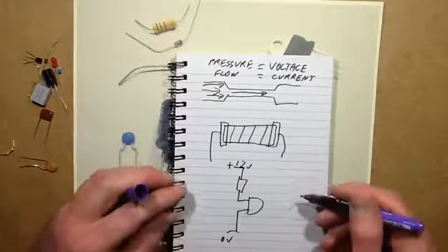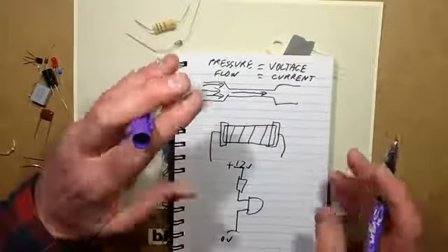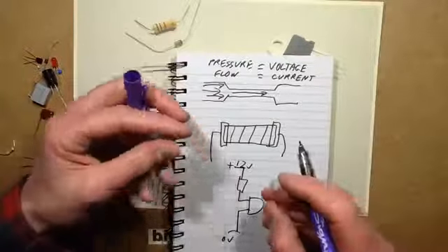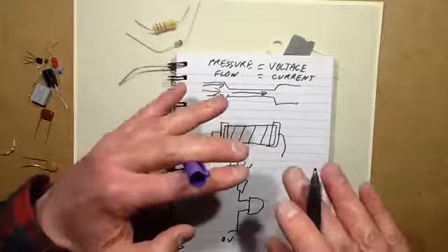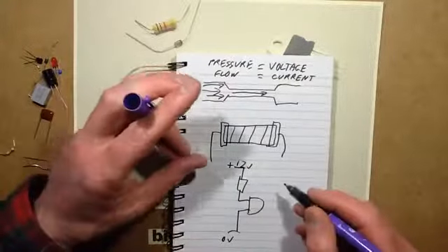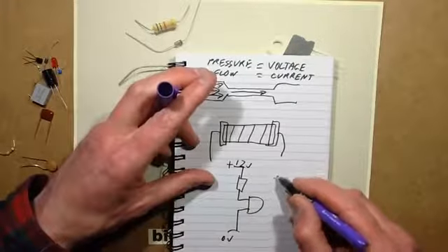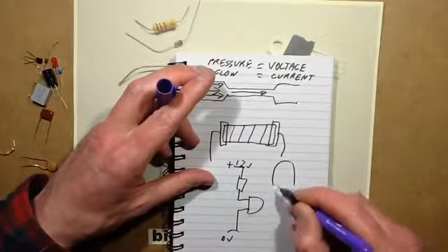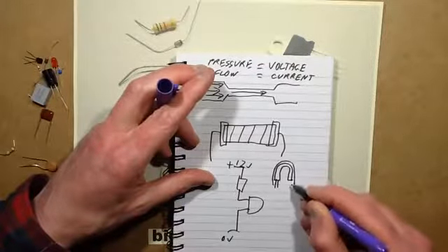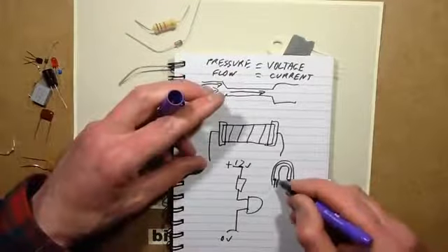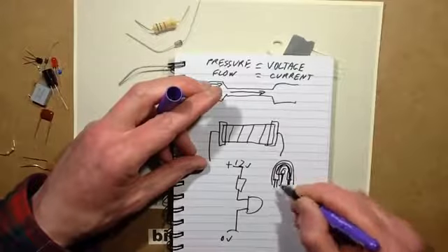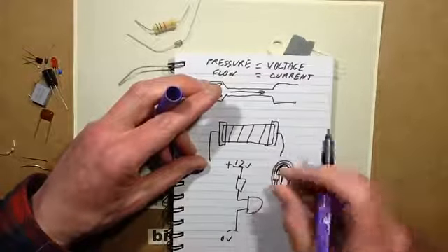They're also used for things like time delays. You might have a resistor charging up a capacitor, it trickles the current into it until the voltage reaches a certain level, and then that could be used as a timing function. And you also get variable resistors where effectively it's a carbon track connected at both ends. You only really need to use it connected at one end, and with a wiper that actually wipes round that track, so that depending on its position, that will vary the resistance.